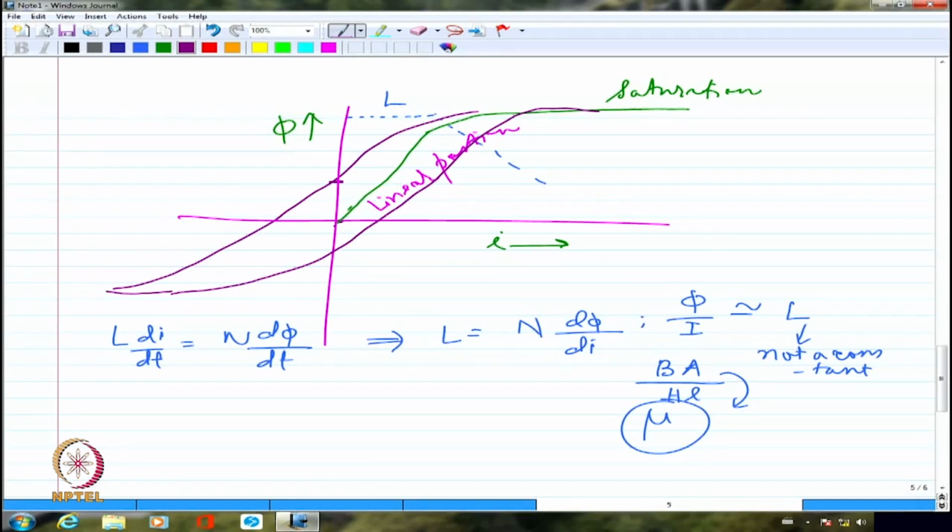Right? So this particular hysteresis property is a pain in the neck in many of the alternating current machines because it will first of all eliminate the linearity. If I simply try to assume that flux and current are linear even in the beginning, that is not going to work. So the linearity property is lost, which will give rise to several non-linear behavior, especially if I want to use this transformer for measurement.